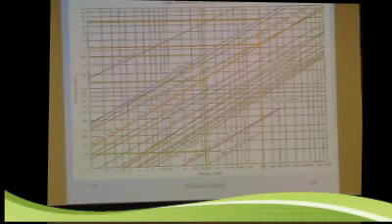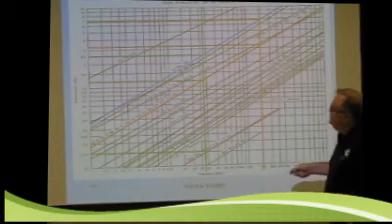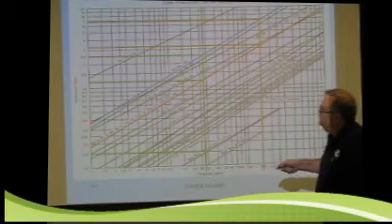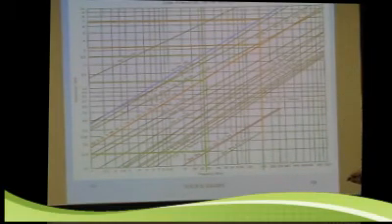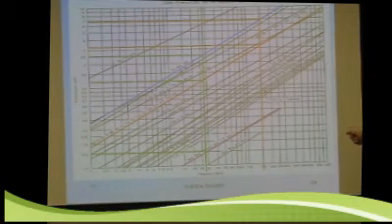This is the chart I was telling you about. It's pretty hard to see. You can get this chart in most antenna books. It is not in your book, and you don't have to have it for this. But essentially, this shows the attenuation in dB. This is how much you're losing. This is the frequency. So just here at 150, you can see how much more you're losing.